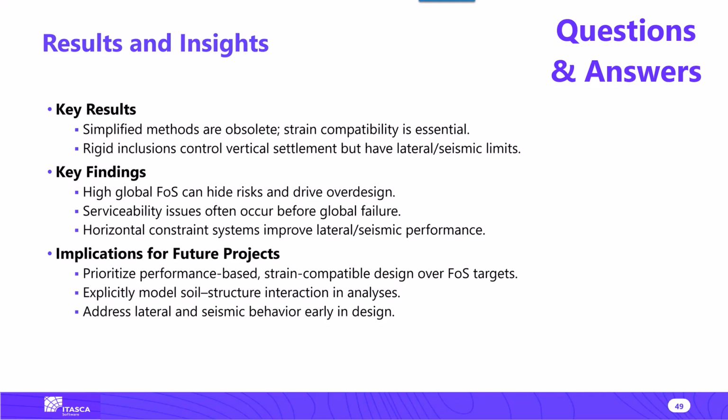And then a follow-up to that was, if yes, what are the main structural, geotechnical, and economic outcomes of such assessments? Again, it depends on the contractor. It depends on the site. In my view, it simplifies all the pile cap placing, all the geogrid, and you just create a working platform, and you drive down the columns or build a column in general, and then you lay maybe a net of steel net and pour lean concrete.